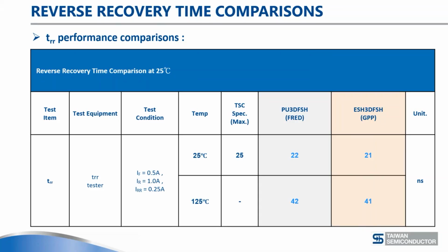In the meantime, we also have explanation notes and application notes on our website, explaining all the parameters of diodes which you can find. The new data sheets for the planar devices will also have values for things like QRR and the peak reverse current, IRRM, to give designers more of a feeling for what the recovery slope and shape of these devices look like.